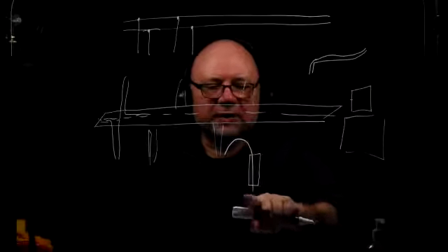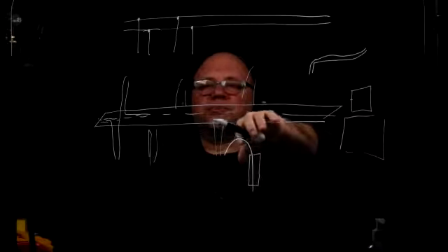So we're basically making a pigtail here. We're going to connect all the blacks, all the reds, and if we have a shield, we're going to continue with the shield. So we're going to connect the shield as well. You can have it shielded or you can have it unshielded. Now, it's not going to affect the performance of the speakers. Sometimes you're going to be requested to put a shielded cable, so the signal that's being produced in the cable is not going to produce interference that could affect other equipment that's in the ceiling.